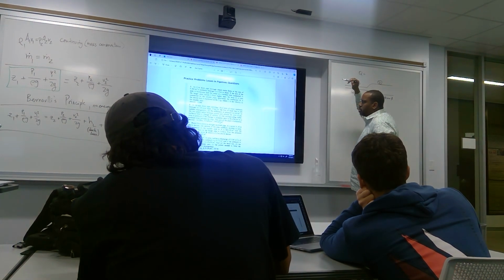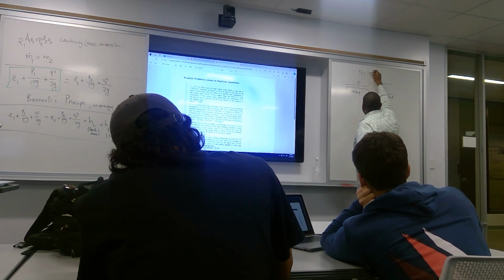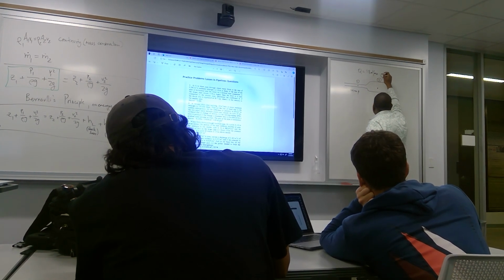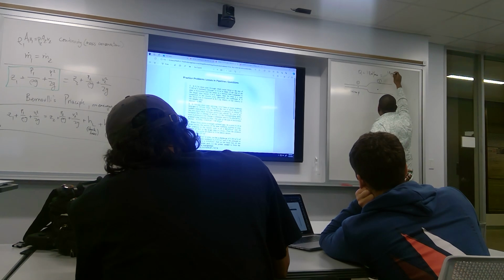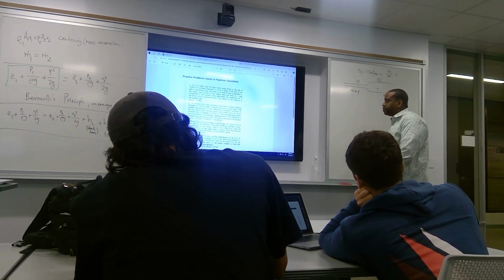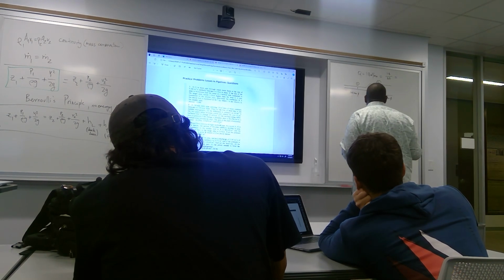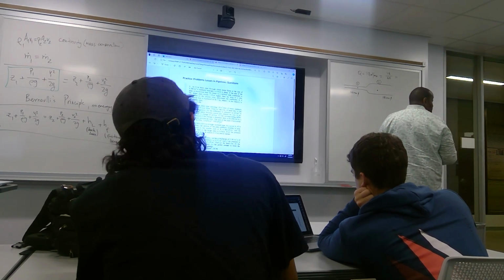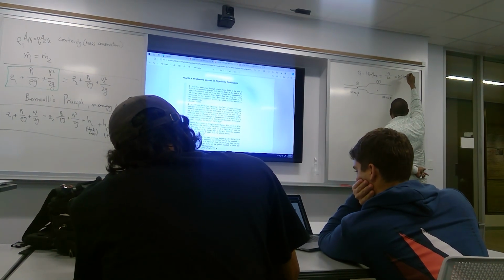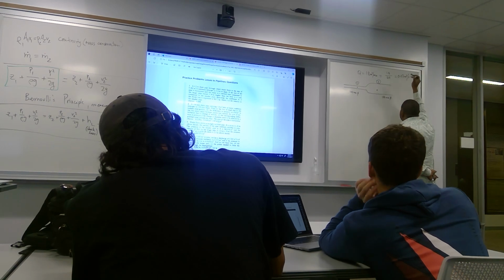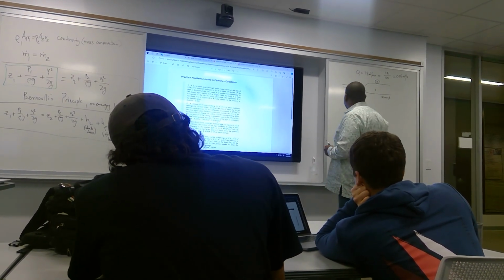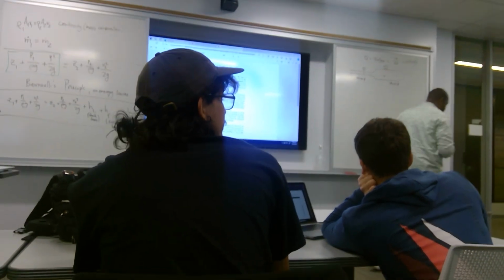They give us the flow rate, 1.8 cubic meters per minute. You can change that into 1.8 on 60. And how much is that per second? 0.03 cubic meters per second. So we want to find the loss of head due to sudden enlargement.